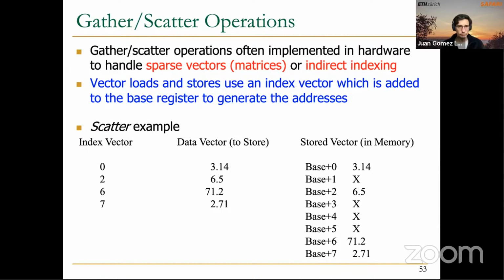So now we know how to operate using vector and SIMD processors in the regular manner when the computation is completely regular. But now we also know how to optimize the access to memory using banked memories. We know how to deal with incomplete vectors when we don't need to use all the lanes in a vector register.